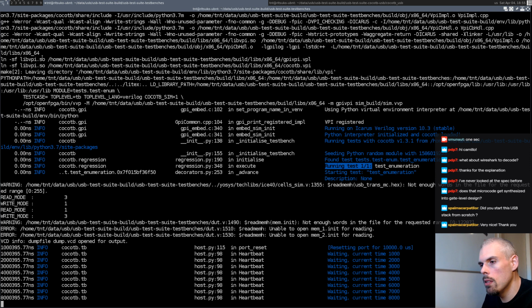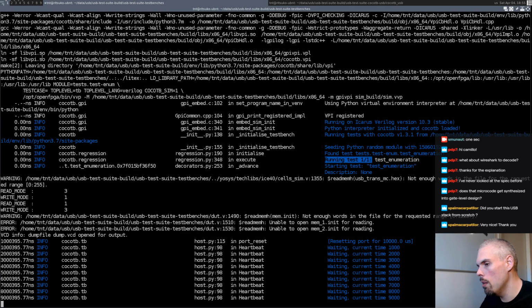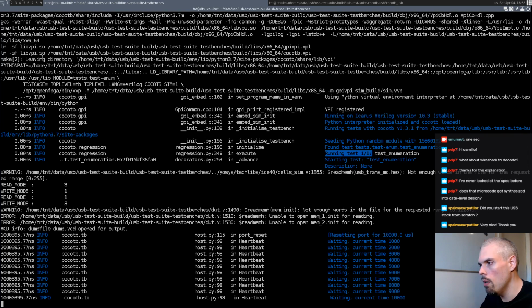I'm also designing an extension for this core so that you can run it without having a soft core. Basically, like a very simple state machine that would just respond to the descriptor requests and would provide like a FIFO input and output, so that you can easily implement USB to serial or USB to pipe data in and out of your gateway without having a full soft core and software stack running.